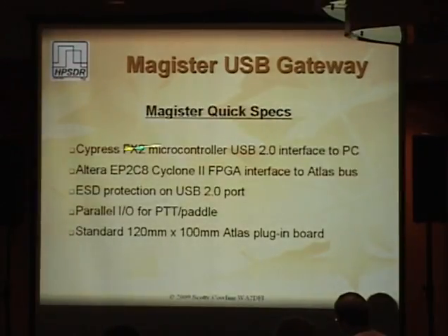Okay, it uses the same FX2 microcontroller, uses the same FPGA. We did add ESD protection on the USB 2 port because we'd had reports of some people burning up their Aussie boards by accident. There was no ESD protection, so we added that. We retained a few I/O bits for the PTT and the paddle inputs, but no extra I/O for the SDR 1000. And same standard size card.